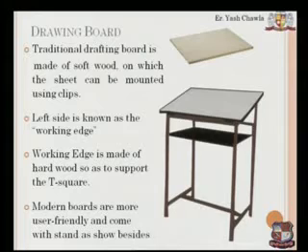How do we define a horizontal line? Well, a horizontal line is a horizontal line. Well, if I draw an inclined line and then I turn my face and see, what does it become? It becomes a horizontal line. So I need a reference to draw a horizontal line. So I use this edge as a reference and use my T-square for marking what is horizontal for this particular sheet. Well, the modern drawing boards come in this particular structure.